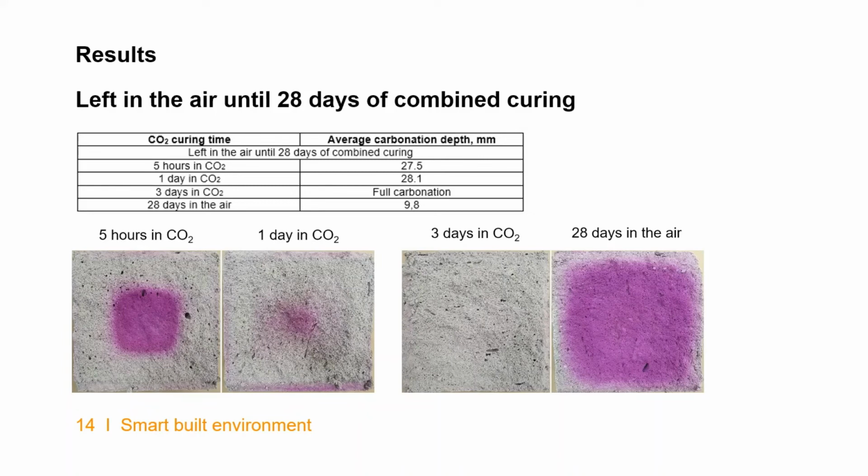After a combined 28 days of curing, we split those samples, and the result we got is that after 5 hours in CO2, the carbonation depth was almost 28 millimeters. After 1 day, it's similar, but once again, the carbonation degree is higher. And after 3 days, it's already fully carbonated.